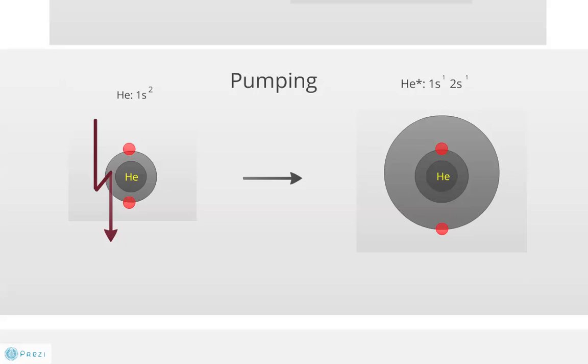The pumping process is induced with the anode and cathode, which are exposed to a high voltage, producing an electrical discharge within the amplifying medium, here indicated with a flash symbol. This causes the electrons to collide with the helium atoms present in the glass envelope. The collision energy of these electrons causes the helium atom to get to an excited state.